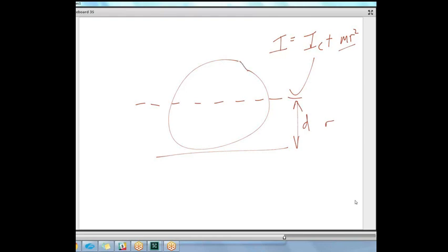And, well, first of all, why do we need an area moment of inertia? Mass moment of inertia told us how hard it was to dynamically spin a solid object. What we might need to know about a two-dimensional cross-section is how difficult it is to bend a cross-sectional shape.